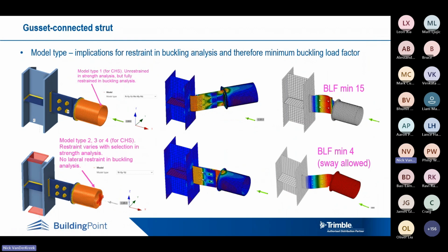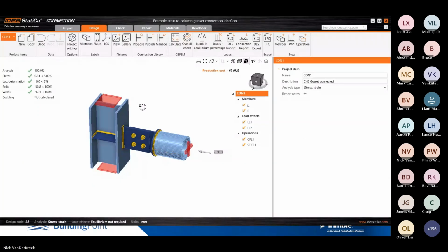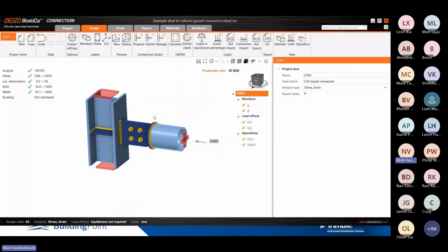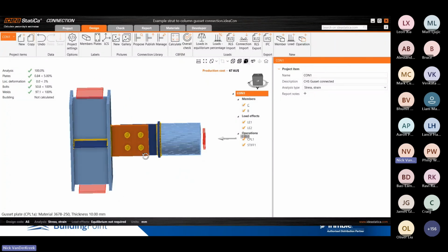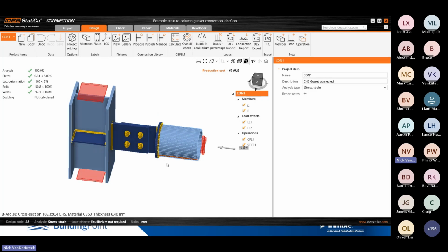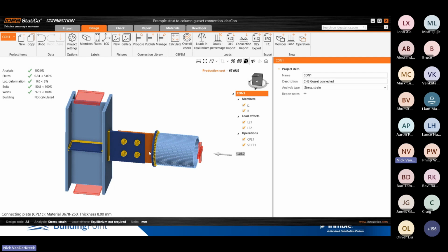Let's go to the software and have a look at that. So here I have the setup. I've been quite casual in the way I've set up this cleat. It's very long. The spacings are too big. This is not good practice, I would suggest. We need to be a lot more careful about this and make it short, these areas that could potentially buckle.